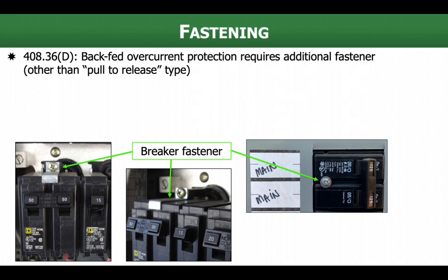So we are required to have breaker fasteners so that you've got to get a tool out. You've got to think about what you're doing here. You can't just whip that breaker off the bus bar and be holding an energized breaker. Presumably, if you're a qualified person, you see there's a breaker fastener, you realize you need to shut down this power source before you do anything on that breaker. There's a couple of examples of different fasteners on the slide here that you can see.